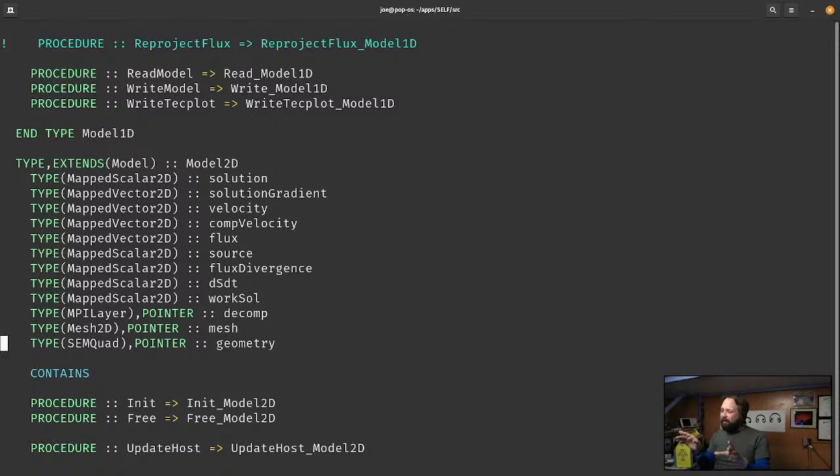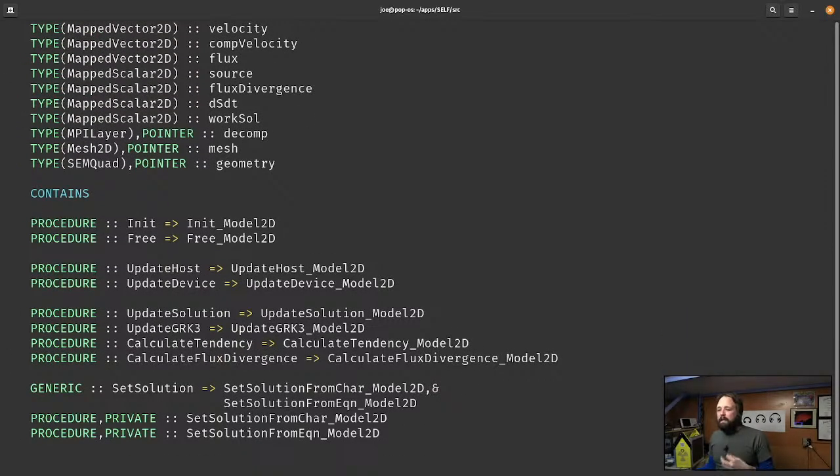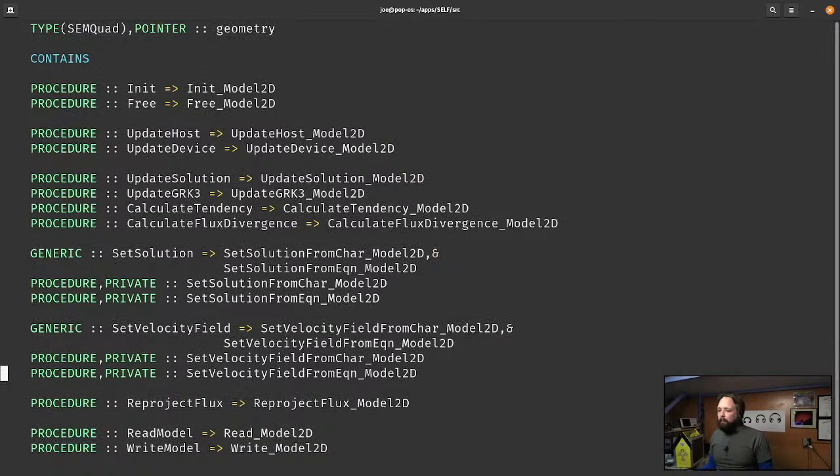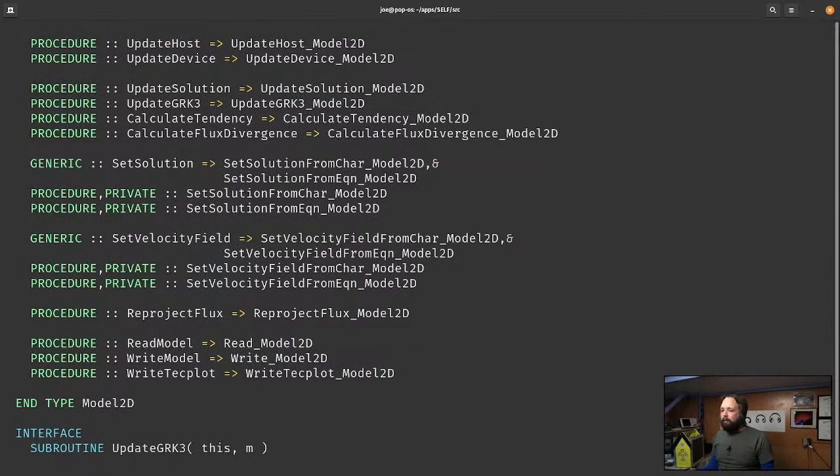Inside of each of those elements, we do coordinate transformations to a reference element and keep track of all the metric terms so that you can do calculus operations in mapped geometries. So SELF is meant to provide you all those tools so you don't have to think about it, and you can just focus on programming up your conservation law solver. The routines you end up needing to define for your particular method are the source term, the flux, the Riemann solver, and if you really want to get into variable boundary conditions, things like that, you can do that. There's also file IO routines that are built in for you.